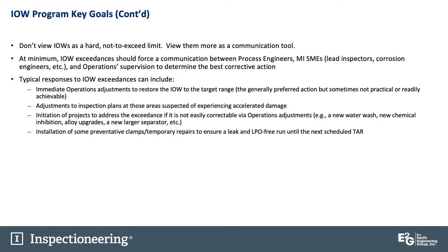So continuing on with the IOW program key goals. Once again, don't view IOWs as a hard not-to-exceed limit. There is some flexibility there, particularly when we assign somewhat conservative target ranges, which we should do. But do, again, view them more as a communication tool. That's really the key goal here.